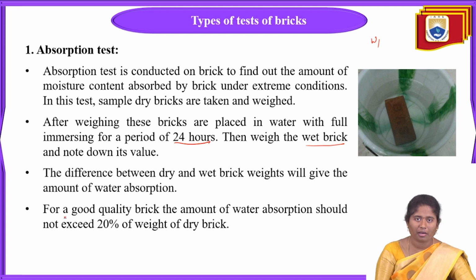For a good quality brick, the amount of water absorption should not exceed 20% of the weight of that brick. That means when we compare the dry brick and the wet brick, the difference should not exceed 20% of the weight of the dry brick.